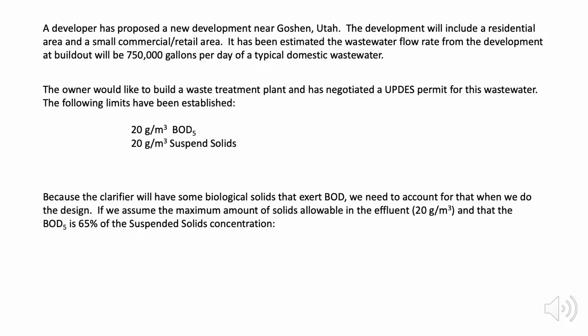That means we can't really design for that allowable effluent of 20 grams per cubic meter. We have to assume that there's also going to be some BOD added from the suspended solids that are found after the clarifier. And let's suppose that we assume that the maximum allowable concentration of suspended solids comes from that clarifier, and up above it stated that we can have no more than 20 grams per cubic meter.